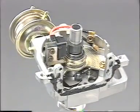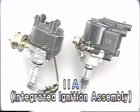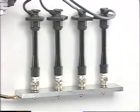This distributor incorporates an advancer device to obtain optimal ignition timing. A distributor with a built-in ignition coil is called an integrated ignition assembly, IIA. The charge from the ignition coil creates a spark at the spark plug, igniting the air-fuel mixture.